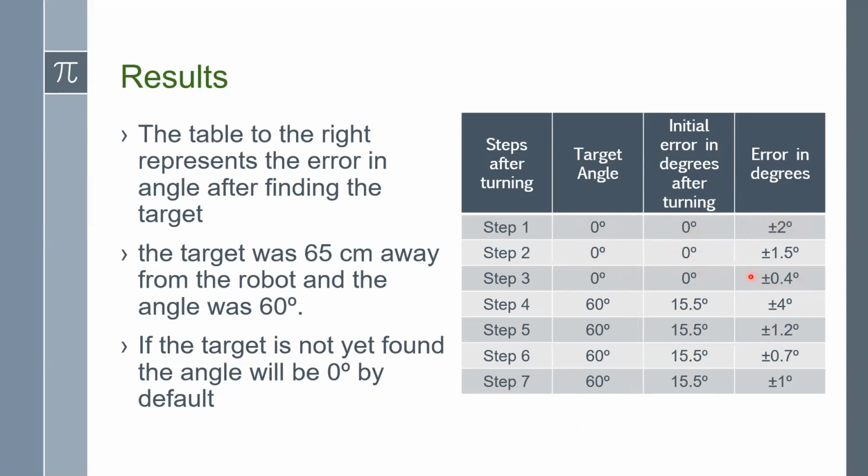There will be a PID, and we use the PID to maintain the robot on track on a straight line. However, the PID still has some errors, and these errors come from different motors alongside the errors coming from the MPU itself. But as you can notice, it's very little, so we can actually ignore it.